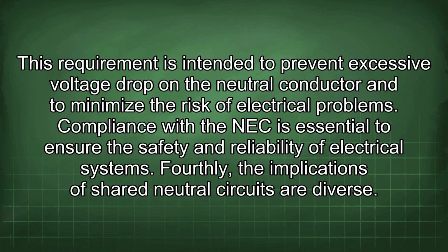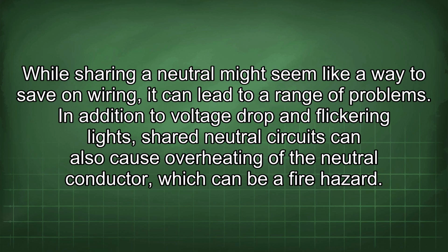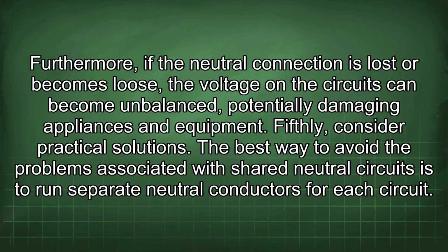Fourthly, the implications of shared neutral circuits are diverse. While sharing a neutral might seem like a way to save on wiring, it can lead to a range of problems. In addition to voltage drop and flickering lights, shared neutral circuits can also cause overheating of the neutral conductor, which can be a fire hazard. Furthermore, if the neutral connection is lost or becomes loose, the voltage on the circuits can become unbalanced, potentially damaging appliances and equipment.